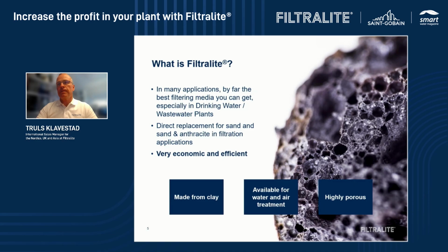As you can see from this picture, you see the structure of Filtralite. It has a high porosity. As I will show later in the presentation, this explains all the benefits you will get with Filtralite. All the benefits can be explained by how the material looks. One thing is the porosity, which is very important for biological filtration, for bacteria and this kind of application. But it's also that the size of each of the grains is different and packed in a completely different way than sand, which we'll talk more about later on.